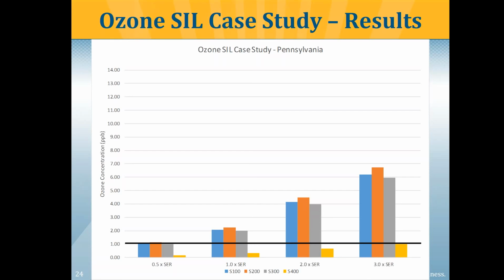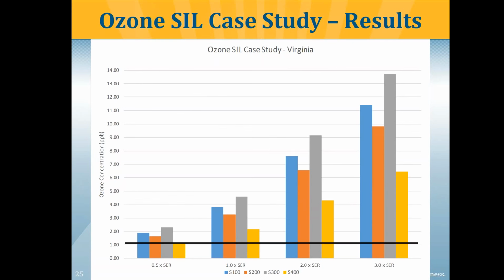And again, to caveat this, because we were trying to emulate different types of facilities, the building downwash configurations and the fence line configuration are also impacting this. Again, the same observation: more sources are going to exceed your SIL value, and the exceedance is high enough that in your full impact analysis, you will have some concern with passing the NAAQS values.